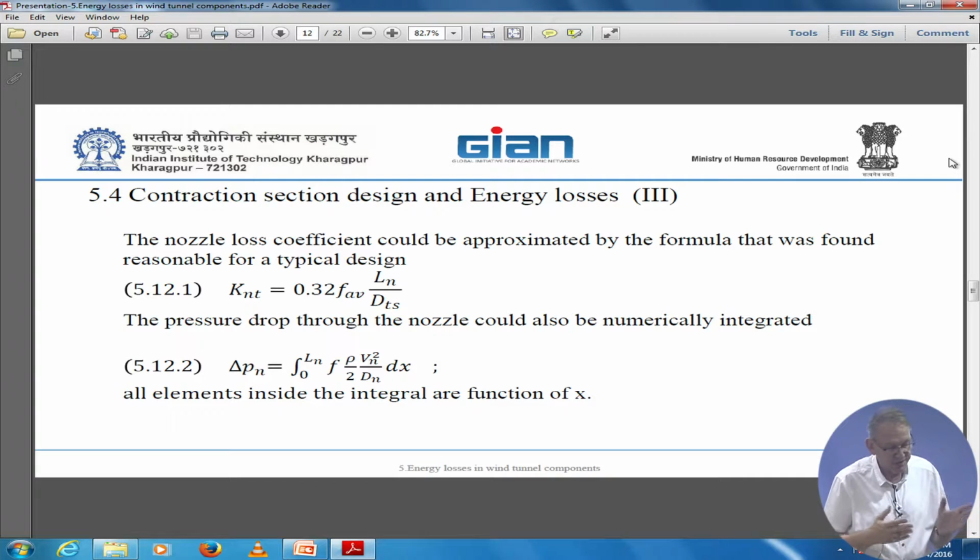So once you have this honeycomb, and honeycomb is cells at the size of several... I mean, in the small wind tunnels, there will be several millimeters. In the big one, it will be a bit bigger. But still, there is the ratio between the diameter of the cells and the length, which should be something like 9.